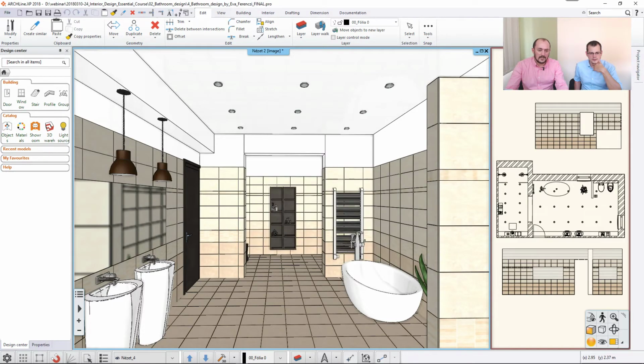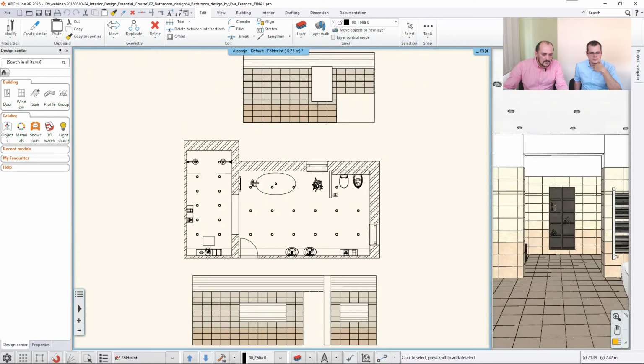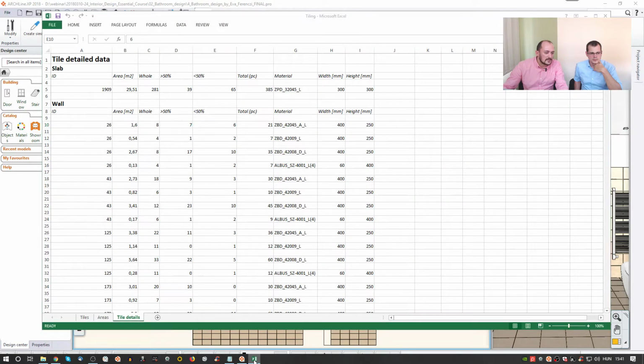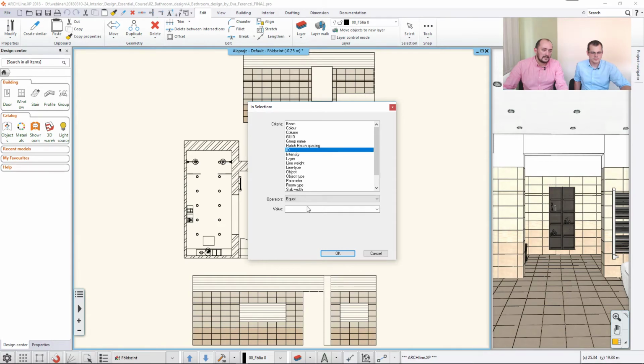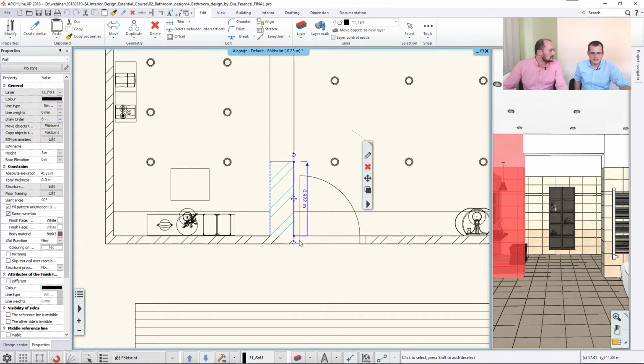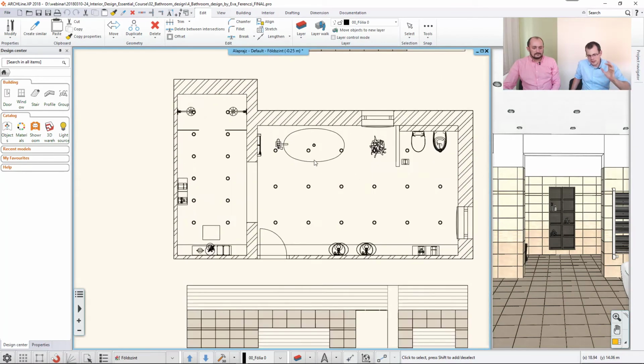So I just click OK, and then the software goes to the 2D. Sorry, I was in the 3D. So I just repeat that. Let's just make sure that it's really 26. Yeah, it's 26. So select by Properties, ID 26, and OK. Now it selects this wall. So it actually tells you instantly which wall piece you are working on. So that's for documentation. It's very good that you get little thumbnails showing how the tiles look, and you get the manufacturer items and the manufacturer sizes.